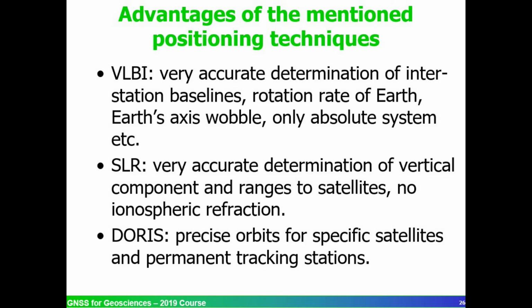Advantages of the mentioned positioning techniques. VLBI: very accurate definition of interstation baselines, rotation rate of Earth, Earth's axis, wobble, the only absolute system, etc. SLR: very accurate determination of the vertical component and range to satellites, no ionospheric refraction. DORIS: precise orbits for specific satellites and permanent tracking stations.